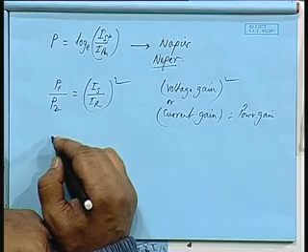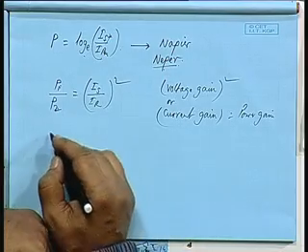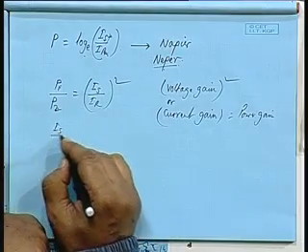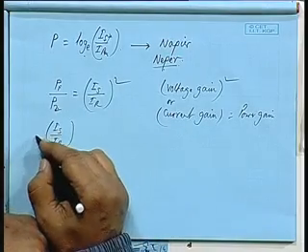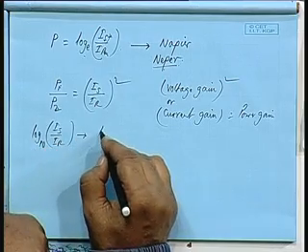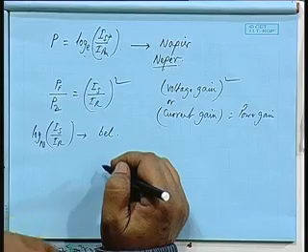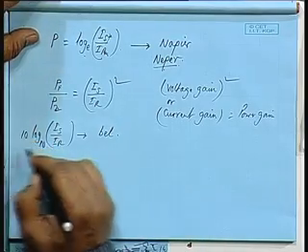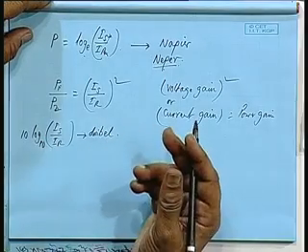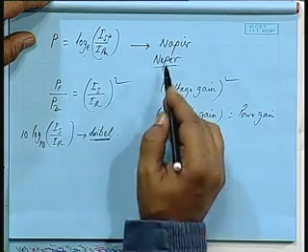Now, we have already done in Bode plot, when we talk about voltage gain or current gain, Is by Ir, log of that with the base 10 was the unit bell, okay, and 10 times that was decibel. So, you take smaller units, a smaller denomination to define a unit. Now, what will be the relationship between decibel and Neper?